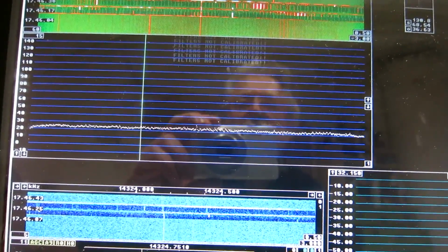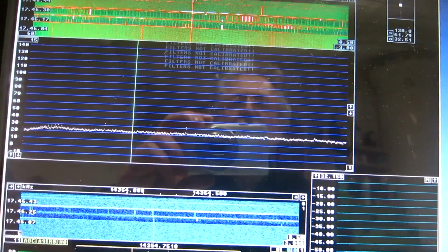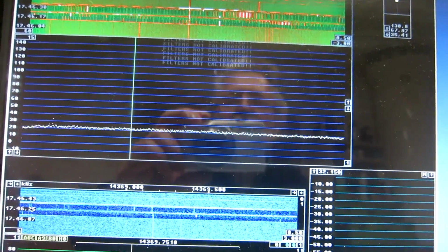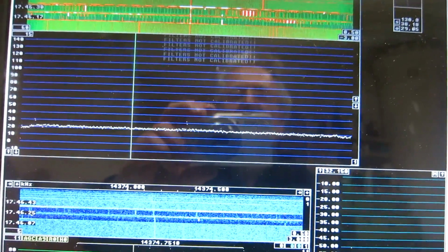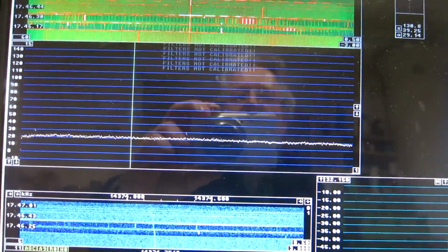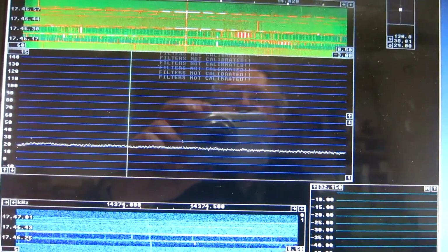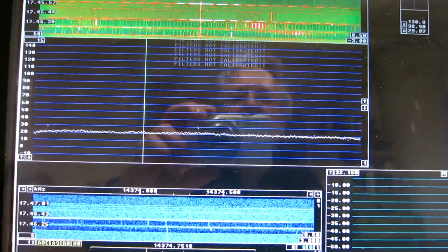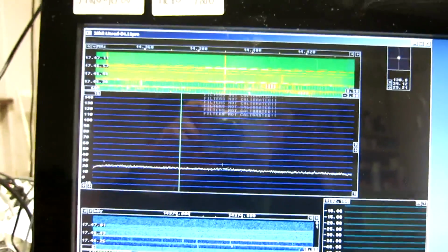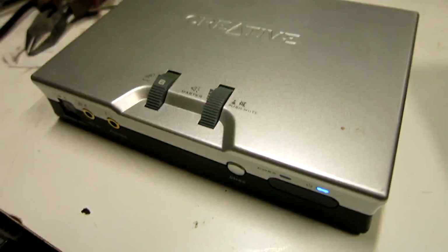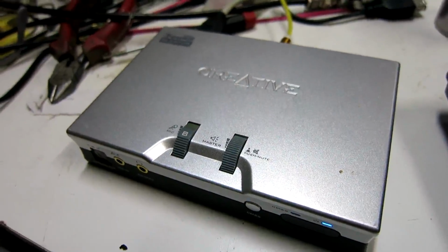So this card is going to cause problems from stations far away from the region of interest. Sound cards are typically sampling at some overtone, maybe 64th overtone at say 6 something megahertz, and then they apply digital filters and decimation. And there is something wrong with the digital filter in this particular box. This one, I think. Or maybe there is some other explanation that I don't understand.